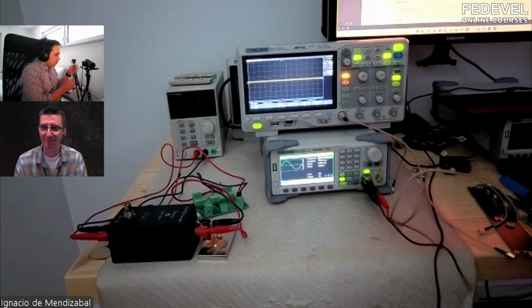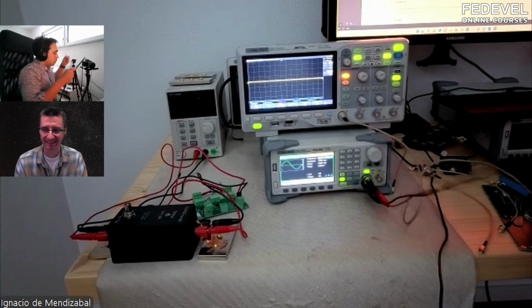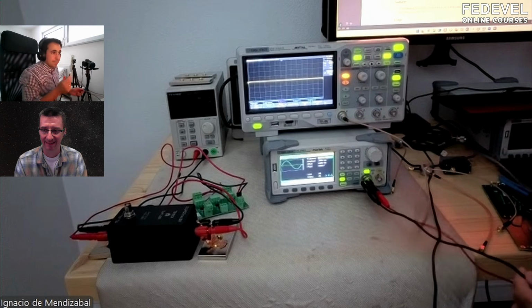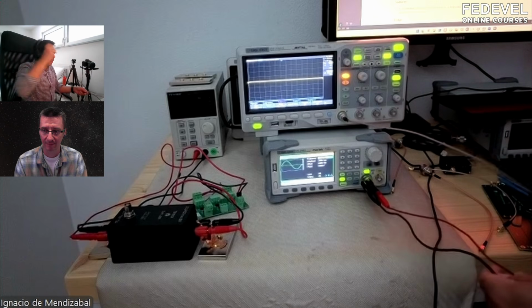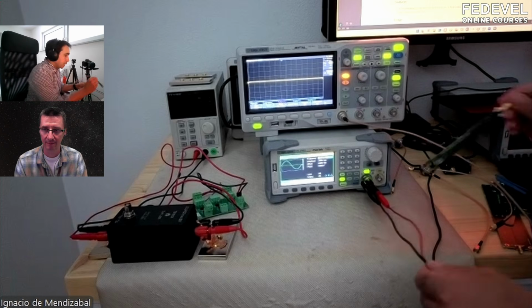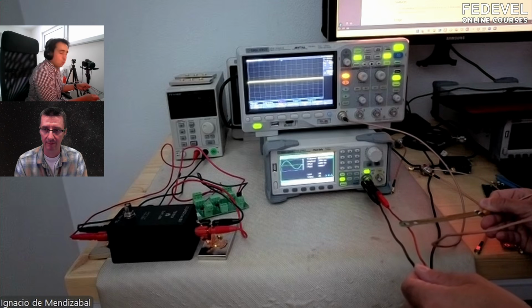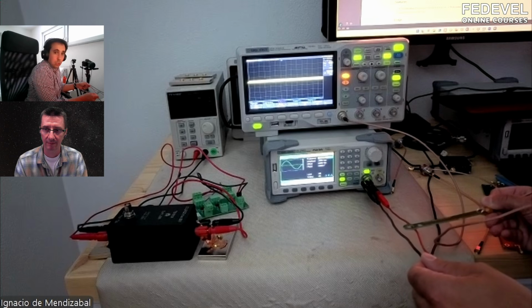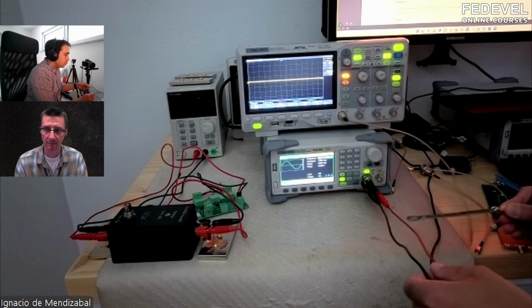Okay, so how do we make this measurement? There are two things that are important. First is the type of probe you use, and also where you place it. Magnetic fields have not only magnitude but also orientation. That means it depends a lot on how you place the probe. This is something that can be against you, but you can really use it in your favor, because in this way you can know where the noise is coming from.